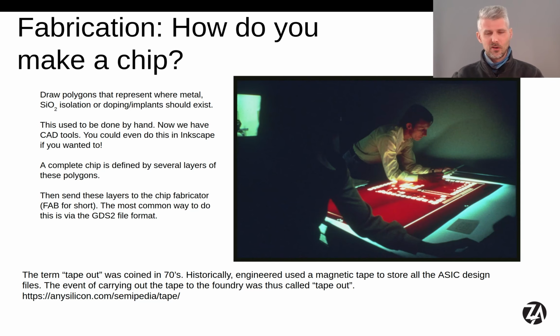You can write Python programs to generate these patterns. But the way that we'll be doing it in this course is using a tool flow called OpenLane, which we'll get to in a later section, that puts together all these standard cells, merges them all, and then exports out the separate layers in the form of a GDS2 file that we can send away to the factory.